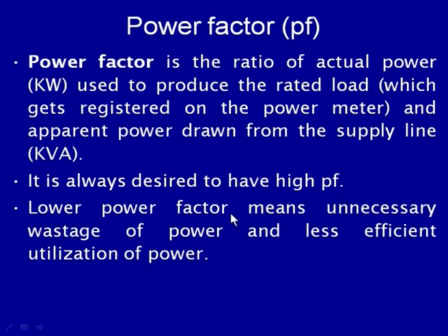A lower power factor suggests unnecessary wastage of the power and less efficient use of the power in an installation. But in case of welding, sometimes we intentionally use a lower power factor, so that we can have the desired smooth, stable arc.